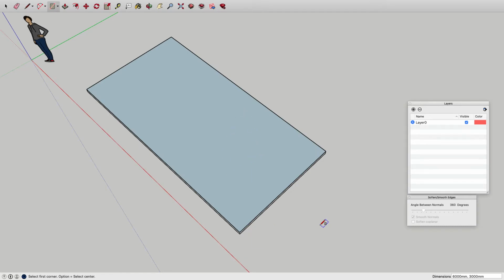Why have I done this? Aha, you'll see now. Okay. Now remember, I have not affected the concrete slab. I'm now going to select the edges. Okay. So I'm going to select that thing that I just drew, triple clicked on it. And I'm going to go to this tool over here called Offset. Check this one out. Click on it. I'm going to click on this edge here. I'm going to move my mouse in from it. And I'm going to type in here 300.